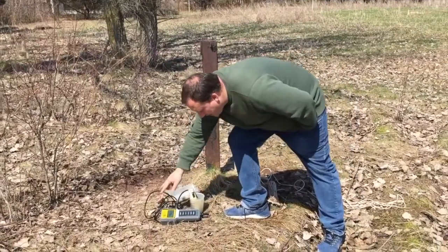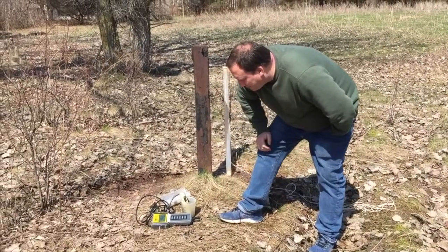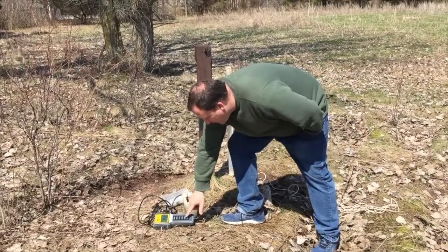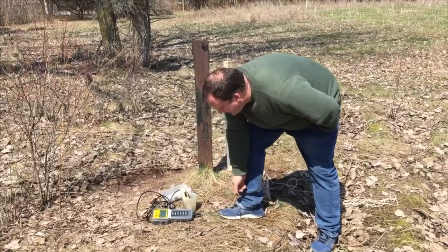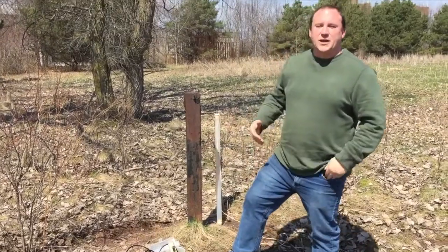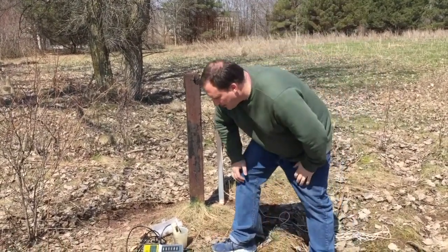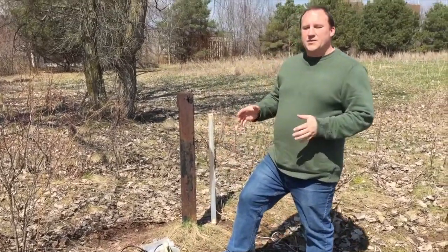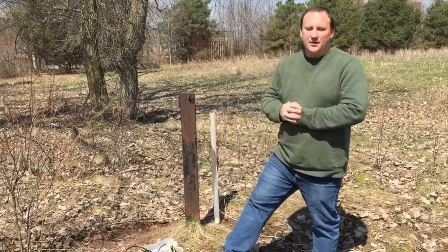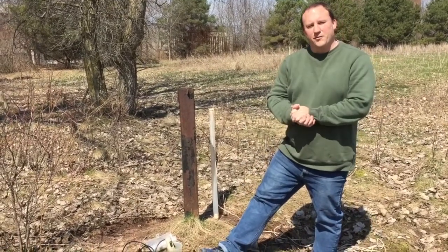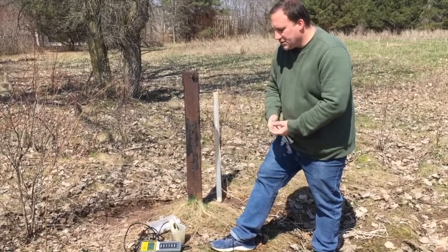This conductivity is not too salty. It's 863 microsiemens with non-flashing. And with flashing, which is an actual temperature corrected conductivity, it's 1214 microsiemens per centimeter. So there are two different ways you can read this. One corrects for temperature, one does not, and I'll let you know what those are like when we do the conductivity. I'll probably give you some for 3 wells at Sunnyside Elementary. But this is basically how this procedure is done.